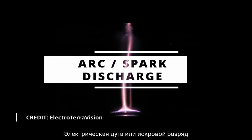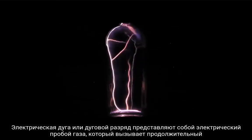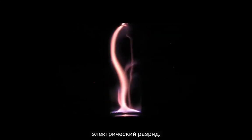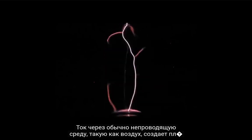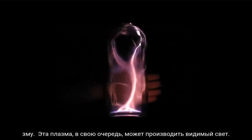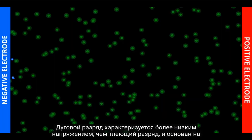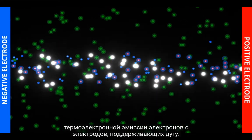Electric arc or spark discharge. An electric arc is an electrical breakdown of a gas that produces a prolonged electrical discharge. The current through a normally non-conductive medium such as air will produce a plasma. This plasma may in turn produce visible light. An arc discharge is characterized by a lower voltage than a glow discharge and relies on thermionic emissions of electrons from the electrodes supporting the arc.